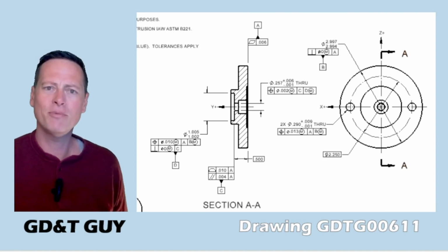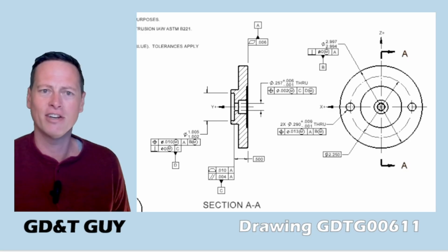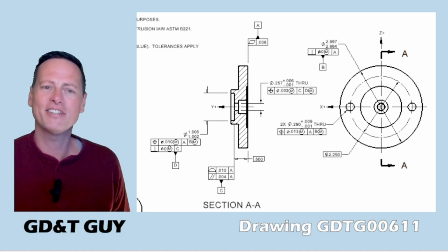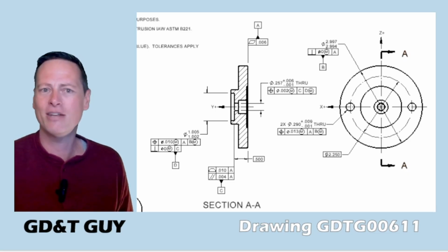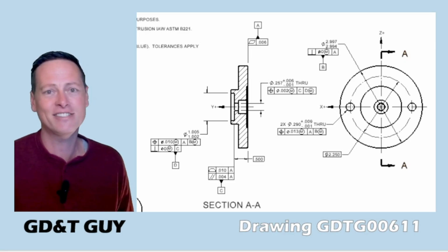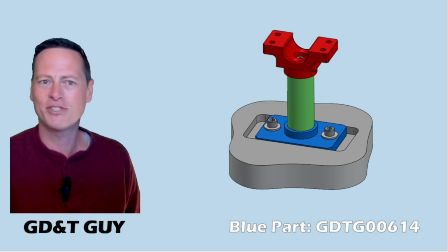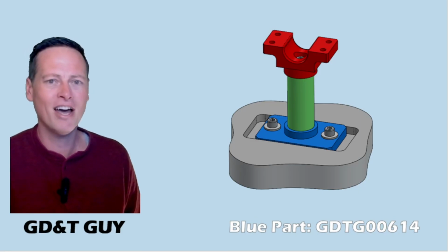So one thing we've learned from these last few examples is that we don't need tertiary rotational constraint for a part like this. That's great and useful, but not exactly life-changing. What's really remarkable about it, I think, is that the standard has now given us at least this one example of a part that has datum features creating constraint in not 6, but 5 degrees of freedom. Well, if a circular part can be fully defined while constrained in only 5 degrees of freedom, can there be other geometries where this applies?